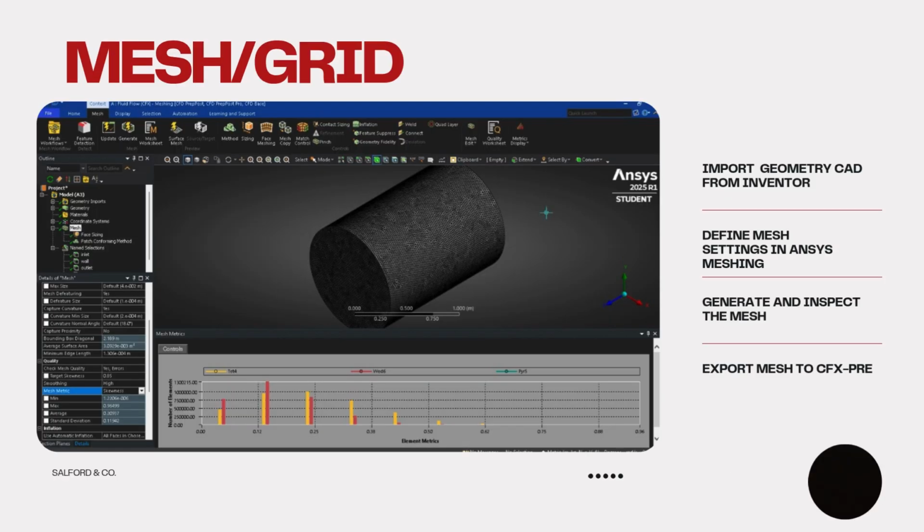So the next part is mesh and grid. After we put the geometry of the Jabulani ball into the geometry section in ANSYS CFX, we generate the mesh using ANSYS Meshing. A tetrahedral mesh was applied to the fluid domain to handle the complex shape of the ball, especially around the seam.